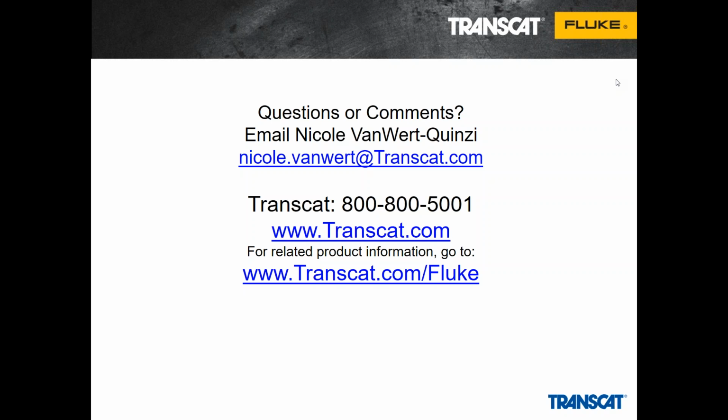I've done a few tests myself with it, and conservatively you could have up to 50 calibrations on a 754 easily. But I would recommend, just for safety precautions, doing a day's worth of tasks and then uploading it at the end of your shift. That's probably the easiest way, but there's enough memory to store quite a bit of calibration tasks and test results.